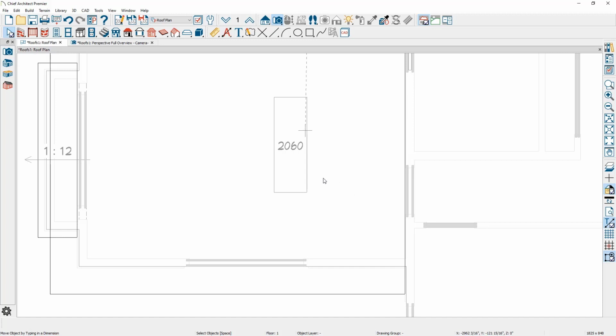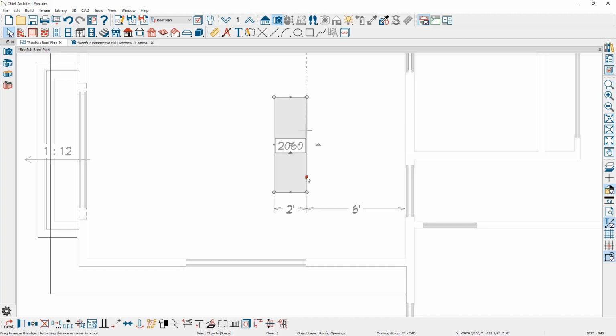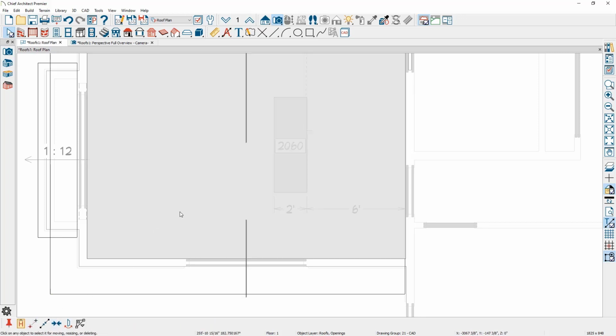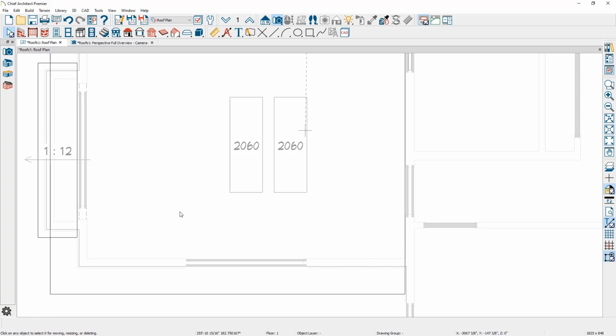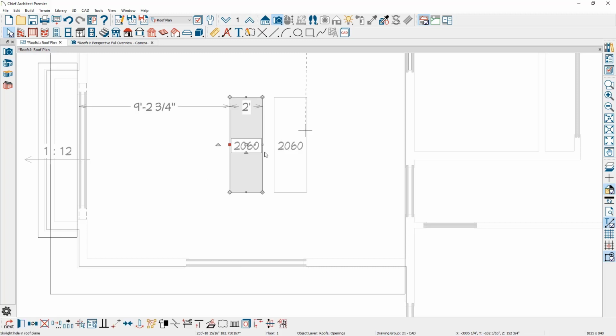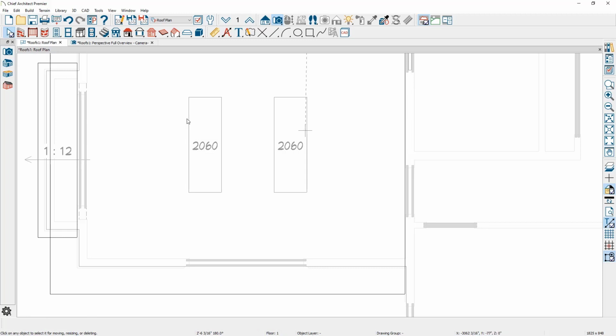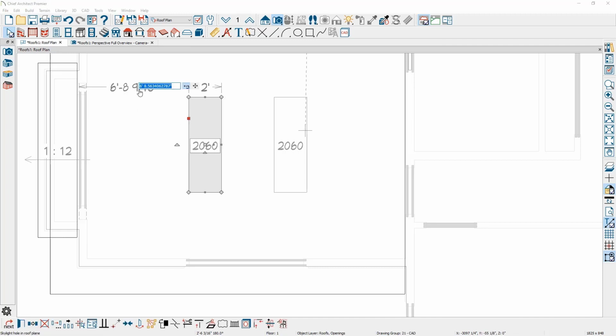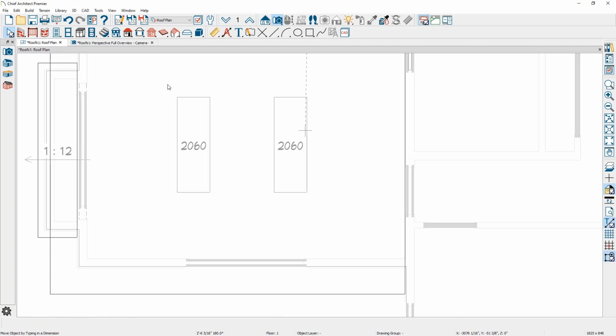Once I have the initial skylight positioned, I'm going to use the copy tool. We'll pick up the center of the room, position that skylight exactly where I want it. Maybe I'll slide it over a little bit further and use the same temporary dimension, and we'll position that exactly 6 feet. Make sure I use the four-way move tool. And that's how I can position those skylights.